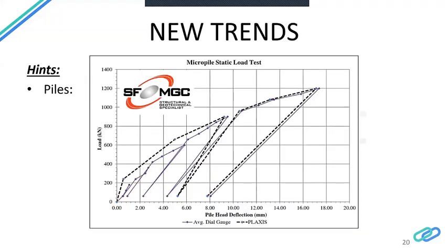Again, for the piling foundation system, you can conduct the pile load test on site and use it, as we said, to calibrate the model. You will get the bearing capacity of the piles from the pile load test. You will get the settlement, and as we said, you will monitor the creep settlement or the creep behavior of the piles, and you have to determine whether it is acceptable or not. And finally, you will use it to calibrate the finite element modeling.